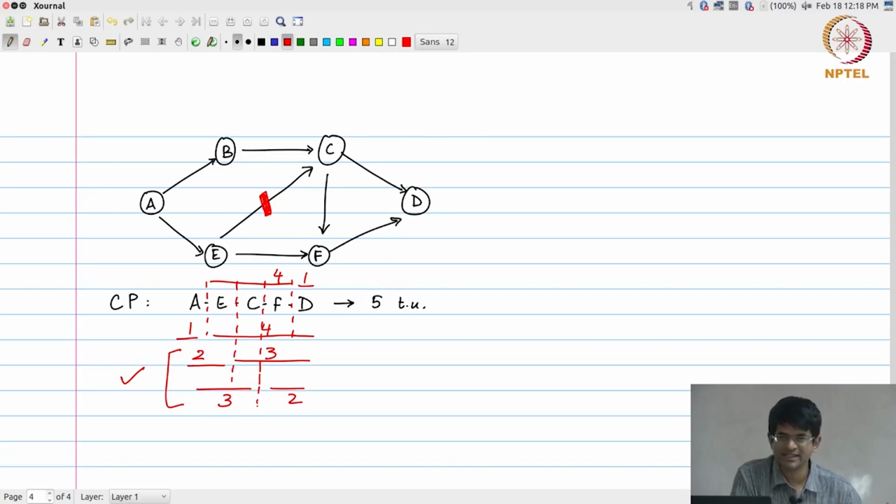If I do not change anything else and just introduce one register over there, I am changing the functionality of my entire circuit, right? If you think in terms of a transfer function, the output transfer function will change. It will no longer be what I expected it to be. It will not just be a sort of delayed version of the input or of the expected output. It will have completely different characteristics. Okay. If I do not want this to happen, what should I do?